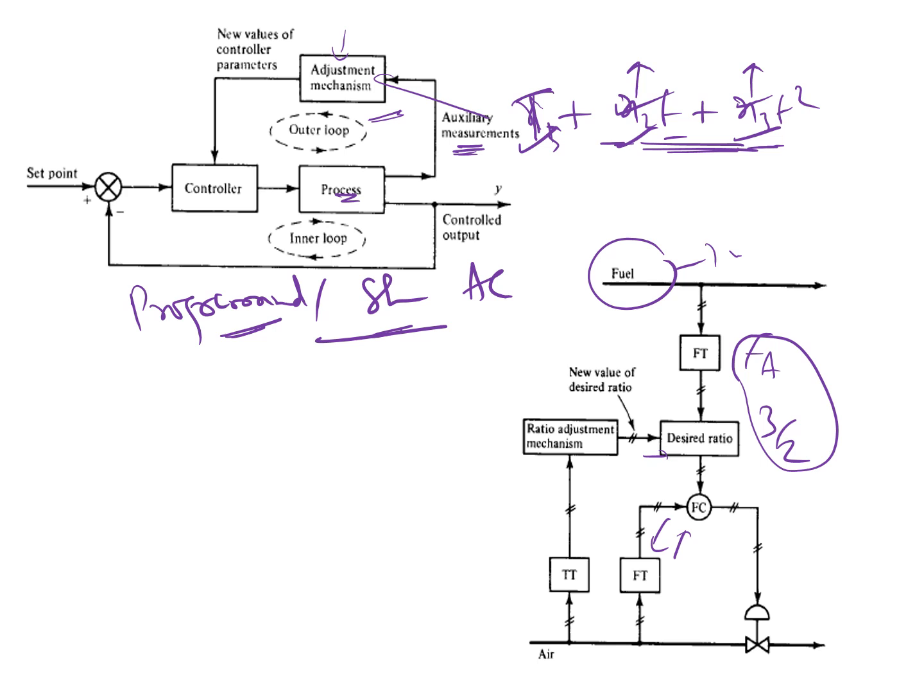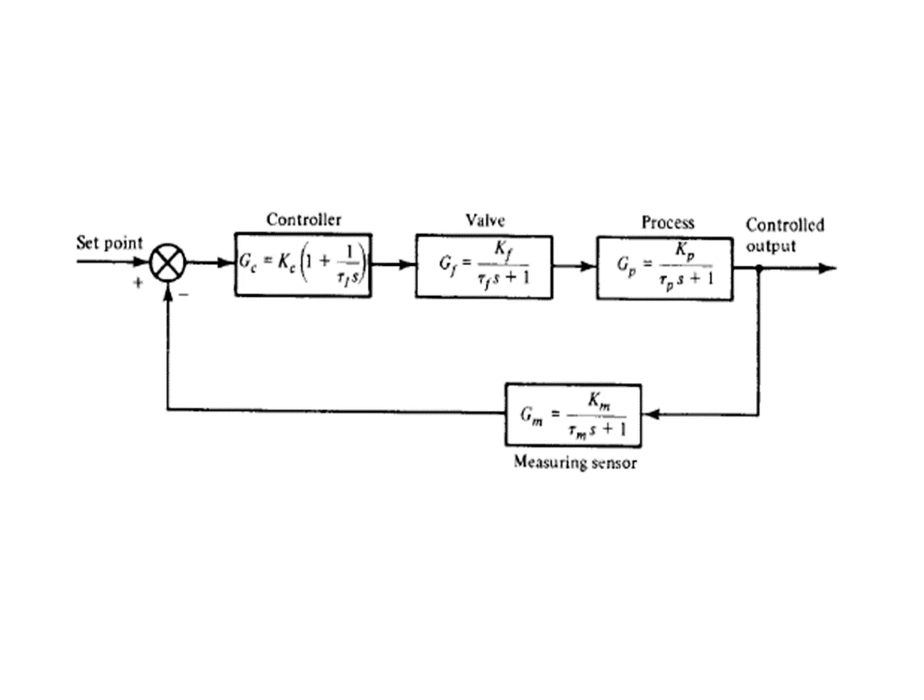For that, without a goal, we cannot change. So for that, we have to use the objective function, which is ISE, or quarter decay ratio, or gain margin or phase margin. So this is how it works. This is called a programmed scheduled adaptive controller. Then the next mechanism is the gain scheduling adaptive controller.